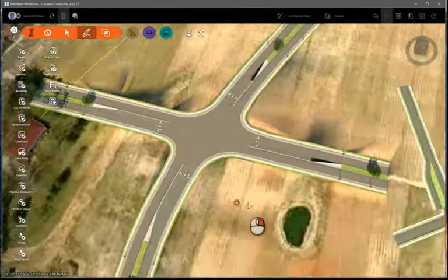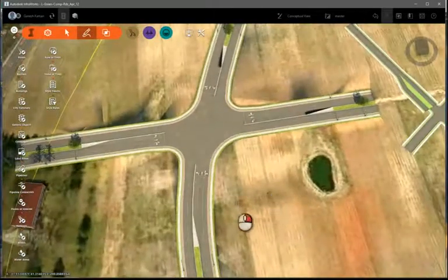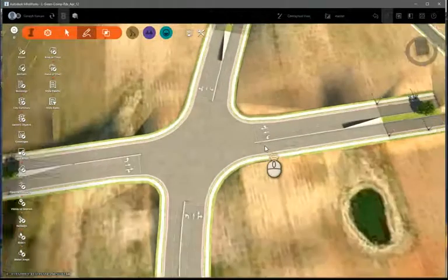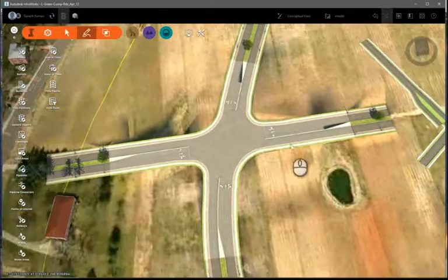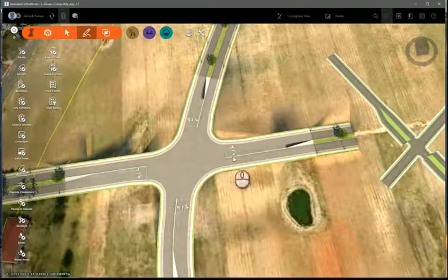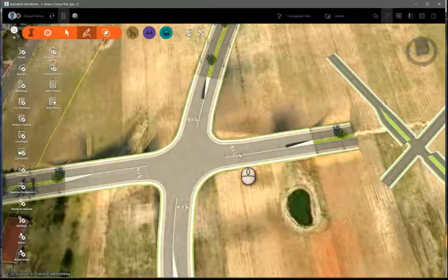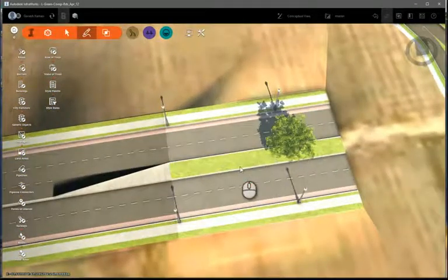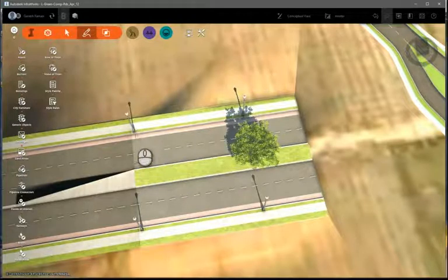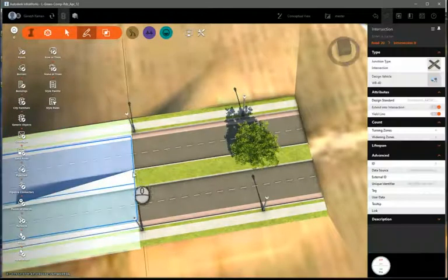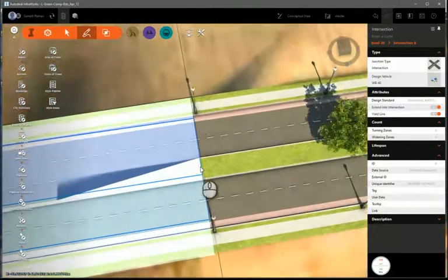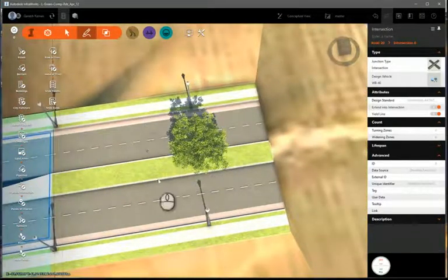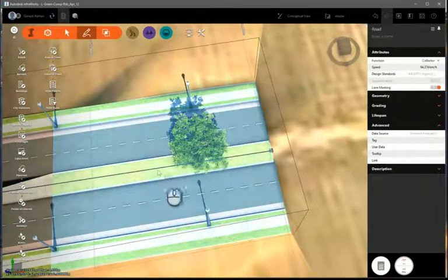So this is the methodology that is going to be used for the project at all the intersections. This same concept can be extended to a T intersection where this lane doesn't exist and a through lane with a T intersection here. So the way to change the style later is to have a split feature at this location where this change of lane stops and change this style into a 2-lane road, 1 lane in each direction with a center stripe of a double yellow lane.